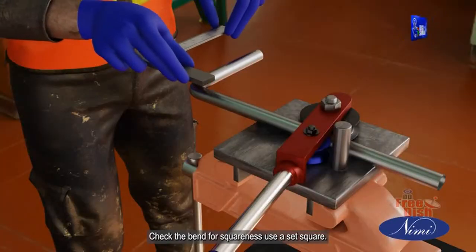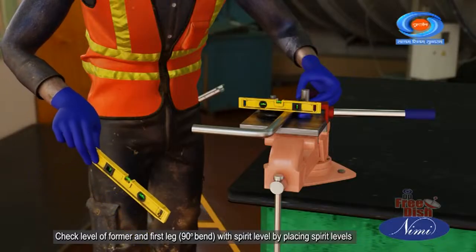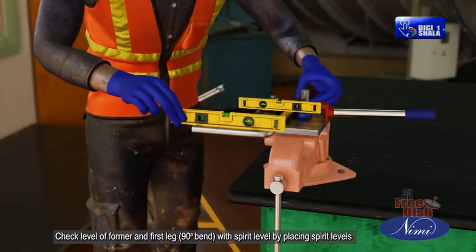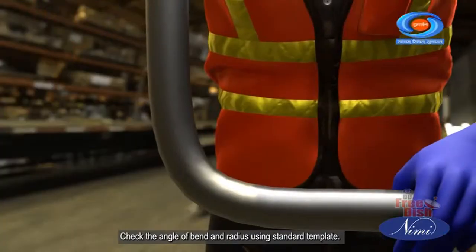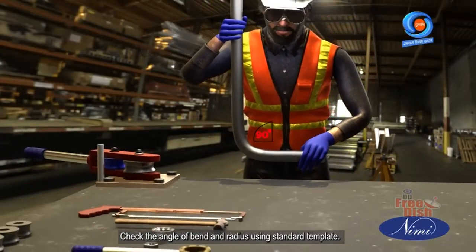Check the bend for squareness, use a set square. Check level of former and first leg of 90-degree bend with a spirit level by placing spirit levels. Check the angle of bend and radius using a standard template.